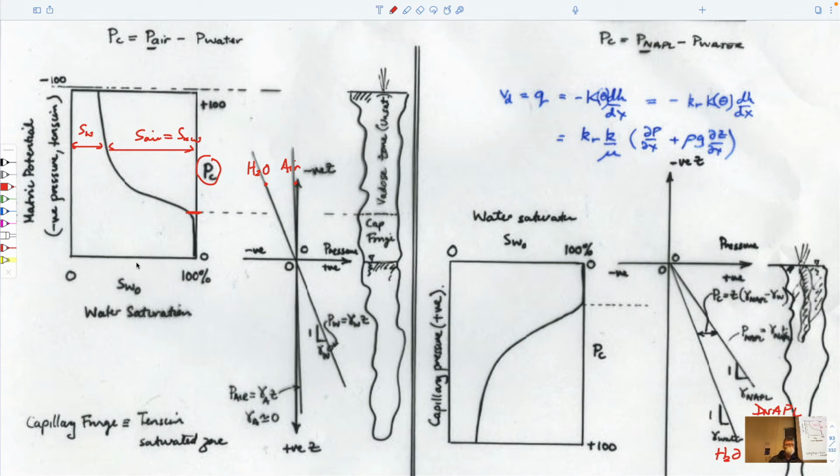And so if we think about what these would look like, it would look like a profile where, if you take a portion of the aquifer up here, you'd think that as a result of that, the relative saturations would be given by this magnitude here. So they would be 30% water, say, and 70% air. So that's exactly what this curve looks like. And so that looks a bit like the chimneys we have, although we've looked at the chimneys in terms of DNAPL, which is a bit different. So let's not go there for the moment.